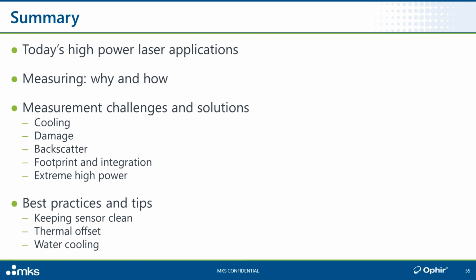And we talked about a few best practices and tips. Keep your sensor clean, only subtract thermal offset when the sensor is in thermal equilibrium with the environment, and some tips about water cooling, most importantly, knowing where that white paper is, how to use Ophir water-cooled sensors.